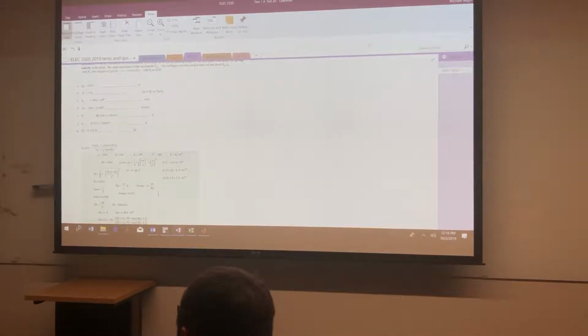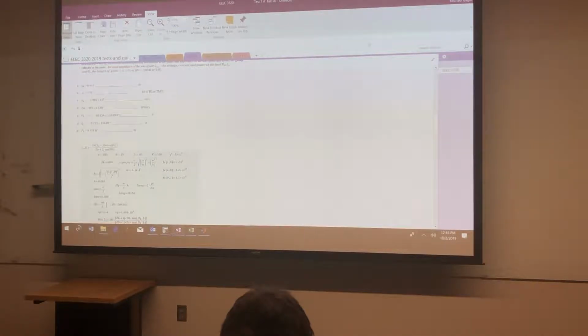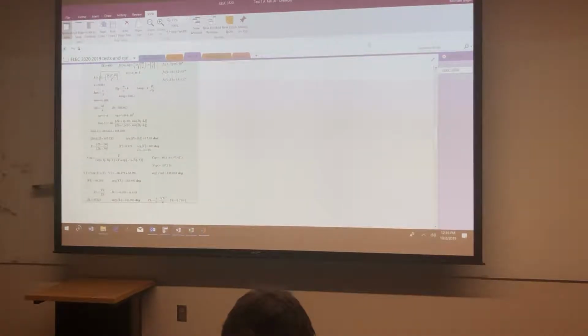So I've got that. So I get wavelength in the guide. Now I get the impedance of the guide. Since it's 1 ohm mode, I know the impedance in the guide, that's right here. It's Z0 here. I know that's going to be eta naught over K. A lot of people got that right. Only a couple messed that up. But it wasn't meant to be hard.